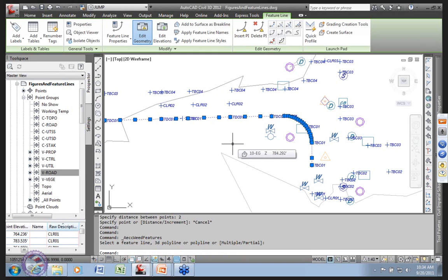So I can densify by using a two-step process, and get a very nice feature line that produces a better surface, perhaps, than the original data had. Did we change anything in the data? Yes. We are, however, using standard engineering practice, just interpolating what was going on, and that will produce cleaner surfaces that print better and give you better contours. Okay, so feature lines play a key part in surface construction. If I had nothing but the points and had to draw them, then I could draw them this way. Yuck. Who thought of this?